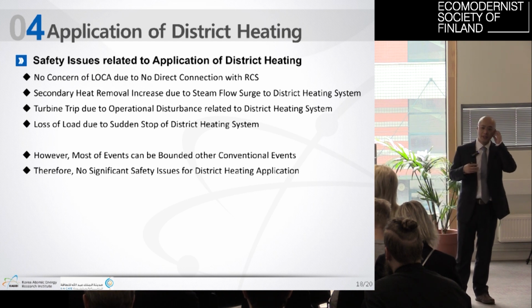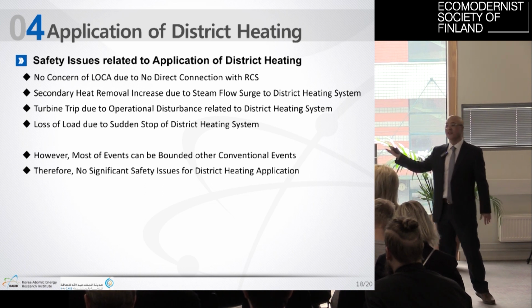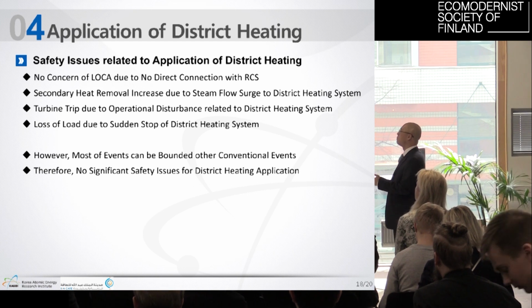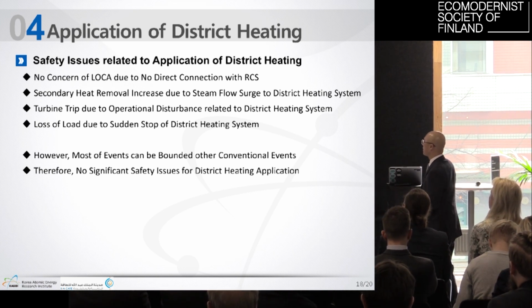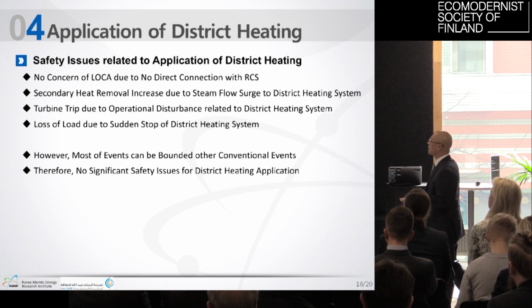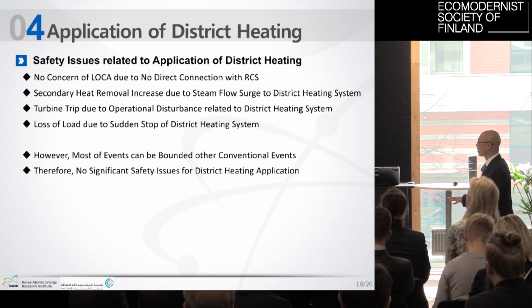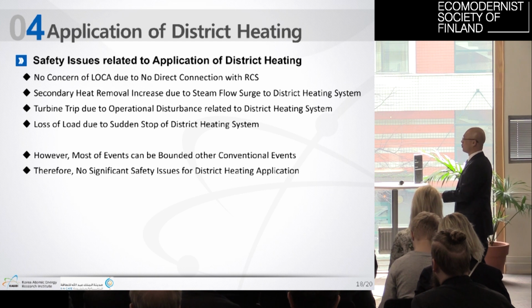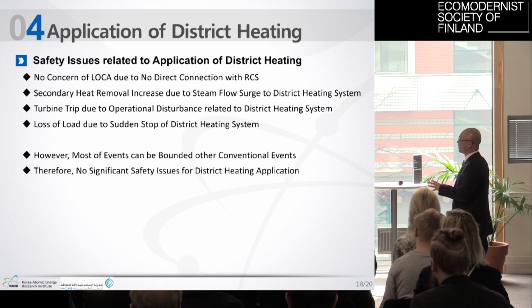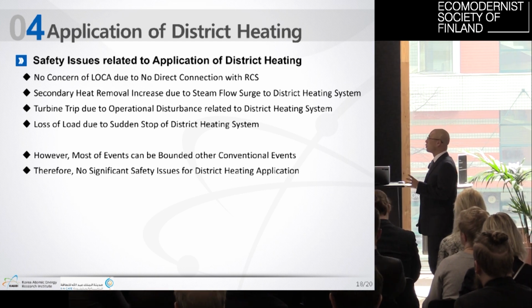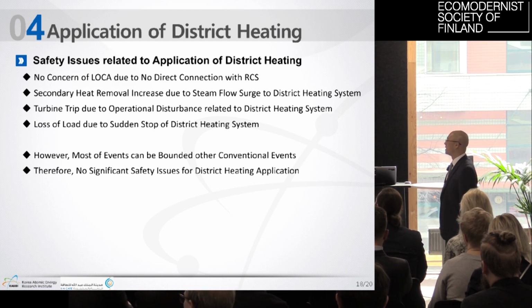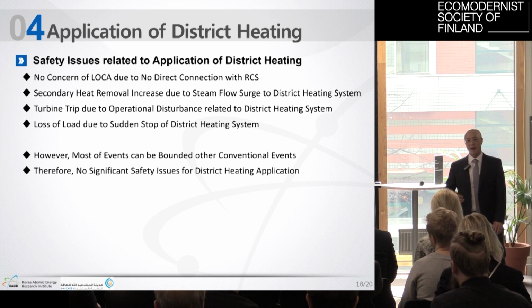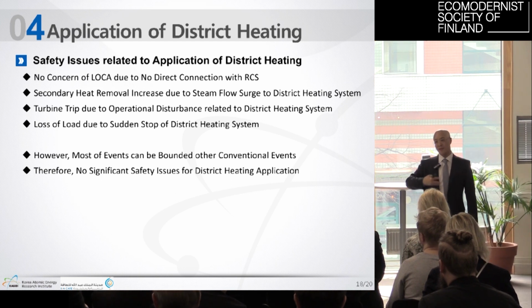However, we have some safety issues for the secondary side: the secondary heat level increased due to steam flow surge to the district heating system, turbine trip due to operational disturbance related to the district heating system, and loss of load due to sudden stop of the district heating system.